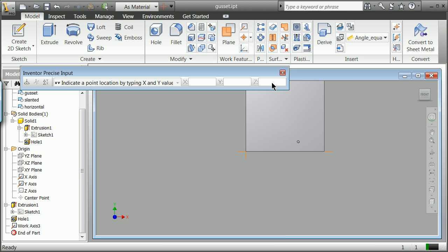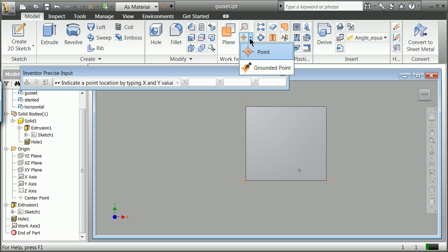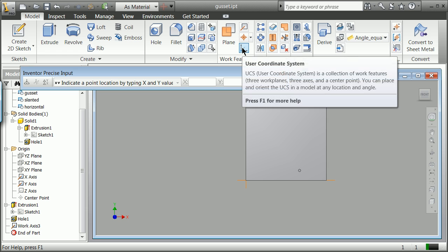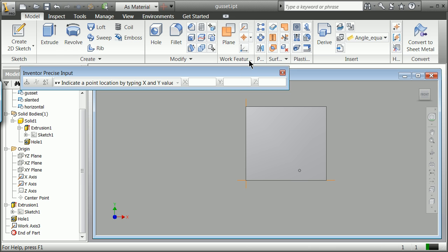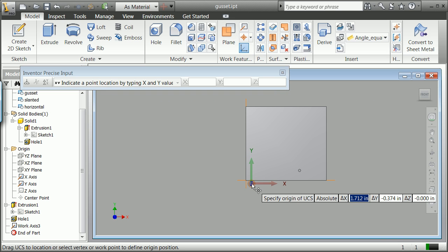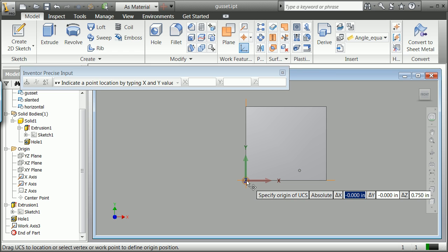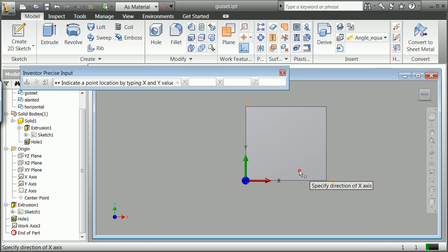The final thing that is going to be very useful on these parts now is to make good use of creating points, planes, and coordinates. So we're going to try to set up a coordinate system if we can right now, and this is where you're going to do a lot of matching of parts together. So I'm going to hit the coordinate there, and I see it there. It kind of wants to go to a particular spot. In this case, specify x-axis. You see I've specified there.